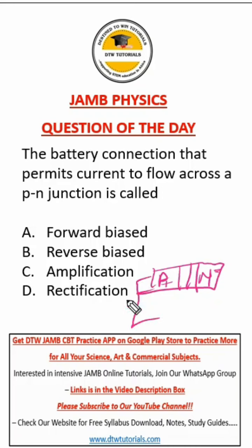Now you have your battery connection to permit current to flow. You are going to have the negative charge of the battery here, and the positive charge of the battery here. So electrons will flow. It pushes electrons across the depletion layer to the holes, and current flows. The only way this happens is in a forward bias system. In a forward bias system, it permits current to flow.